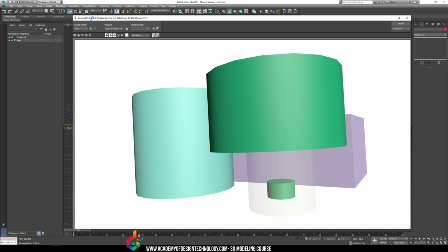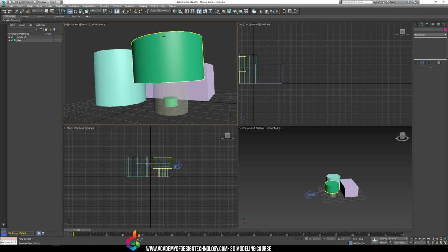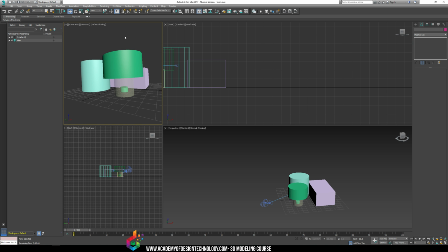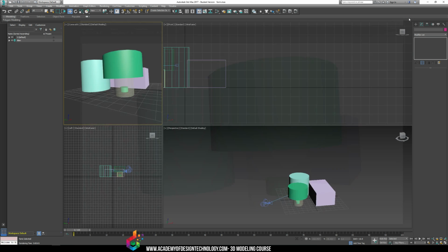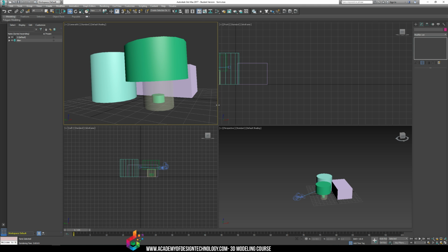So camera 001. And it's saying that we're looking at camera 001 in the quad 4 viewport right here, which is great. You're going to notice something as well that you might see. If I have my viewport this size, watch what happens. It's the same exact render. It didn't change my render based on my viewport size. It's actually rendering 1920 by 1080, even if it's outside this viewport range.